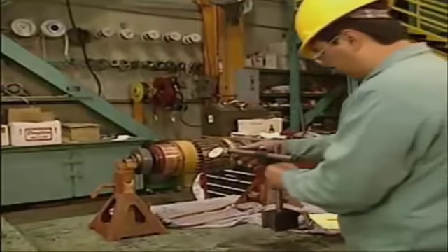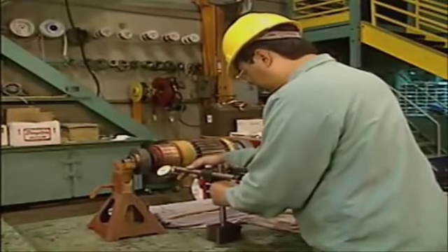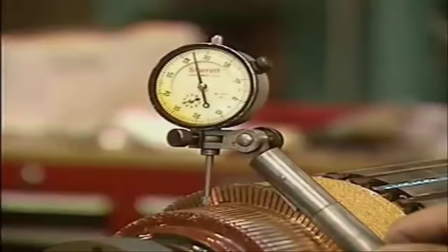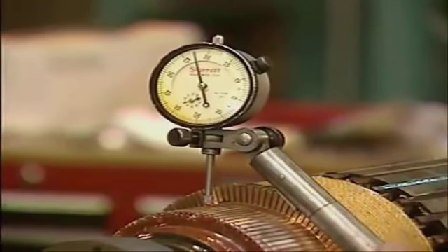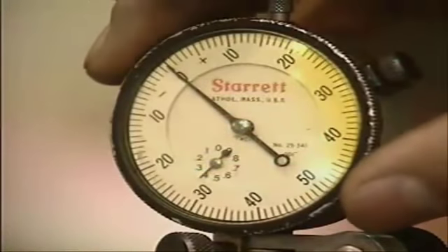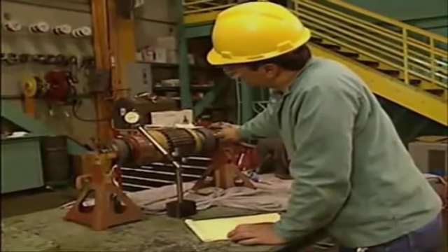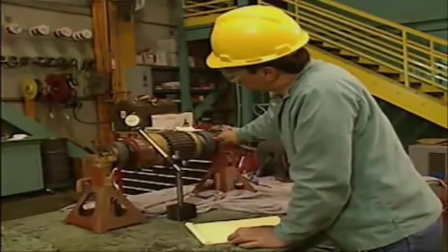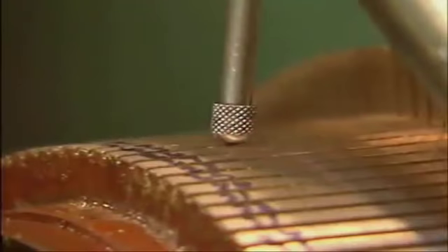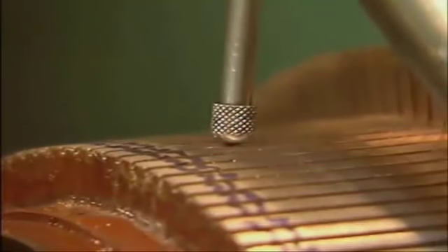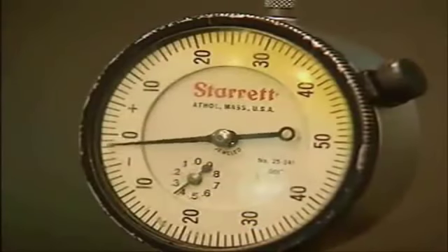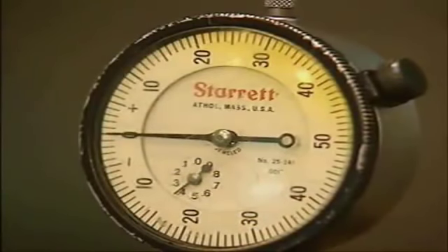A dial indicator can be used to check the commutator for trueness. In other words, to make sure that all of the segments are level with each other. Each segment is numbered to identify them, and then checked with the indicator actually on each segment. The armature should be rotated very slowly, and the readings should be recorded accurately. As a general rule, if the difference between individual commutator segments exceeds 0.002 inches, the commutator must be machined or